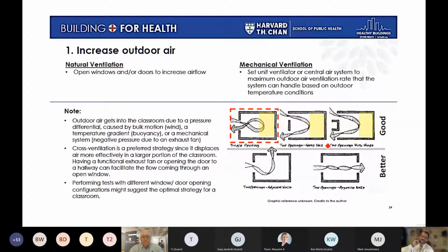In fact, we really run into a big problem if the wind is blowing from that side of the building, because the outside air particles could be much higher than the inside air particles. Just because the outside air has good oxygen to replace the rising CO2 does not mean that it's free from particles. And our concern here is, by opening up these windows without filtering the air coming in through the window, we could be entraining much higher levels of particles into the environment, and those are the particles that the virus likes to ride on. And so that is one of our concerns.